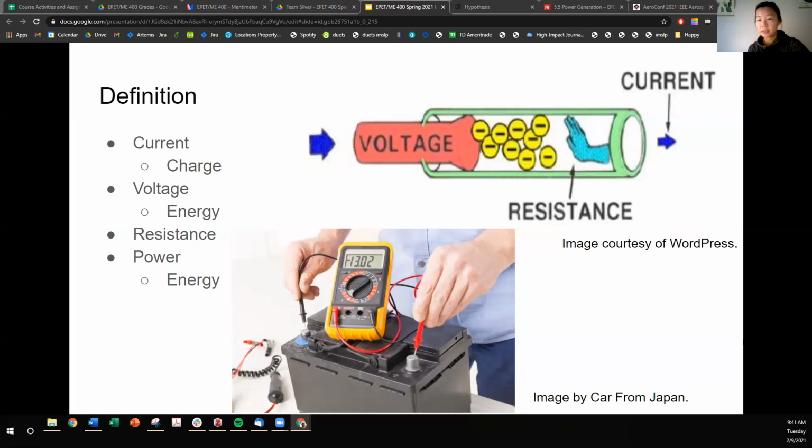Objects made of electrical insulators like rubber tend to have very high resistance and low conductivity, while objects made of electrical conductors like metals tend to have very low resistance and high conductivity. This relationship is quantified by resistivity or conductivity. The nature of a material is not the only factor in resistance and conductance, however. It also depends on the size and shape of an object because these properties are extensive rather than intensive.